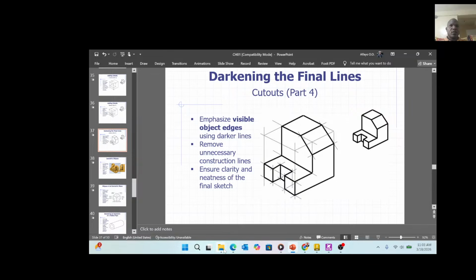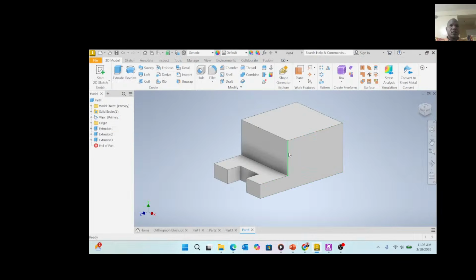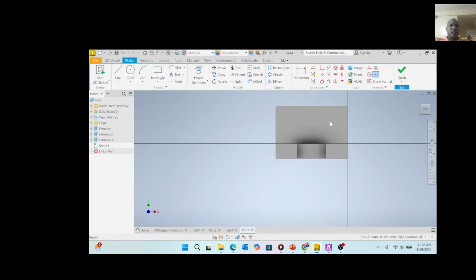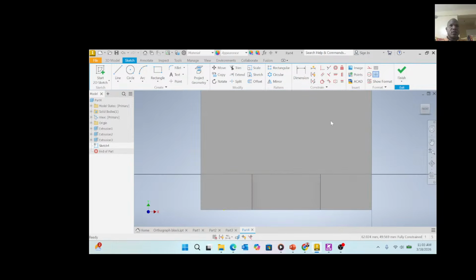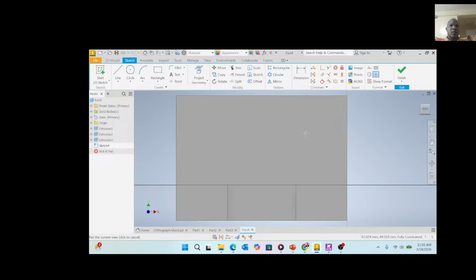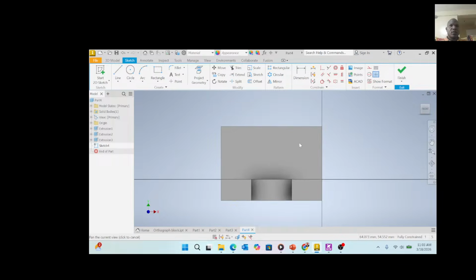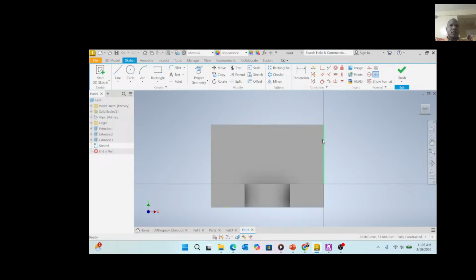So straight away, what we just do is take this surface. You can use this surface. Okay, I can just use this surface to sketch and use it to draw. Let me zoom so it's visible to you. Okay, and there we are. It is this corner that was cut. So that kind of cutting, we call it a chamfer, chamfering the angle.